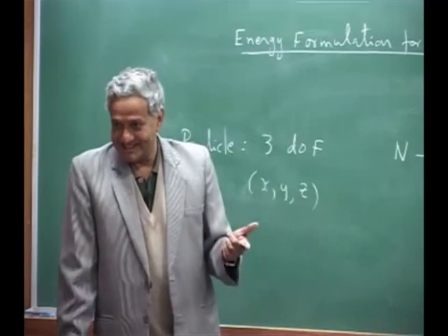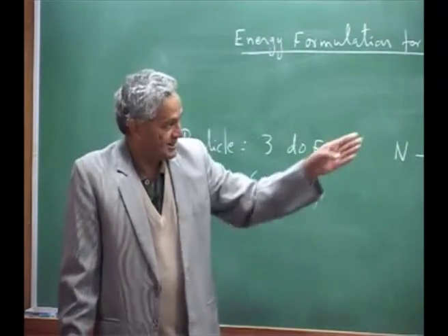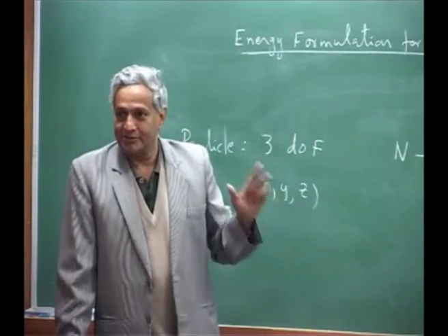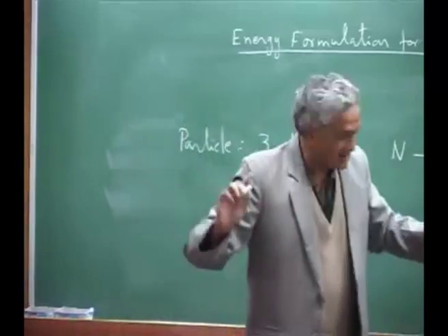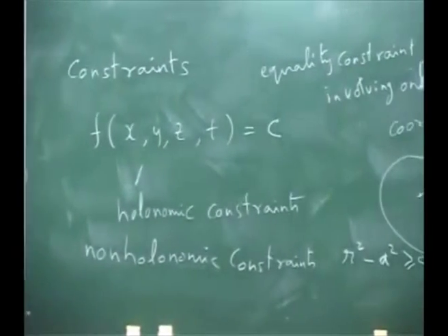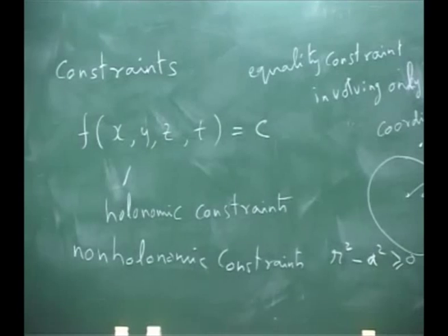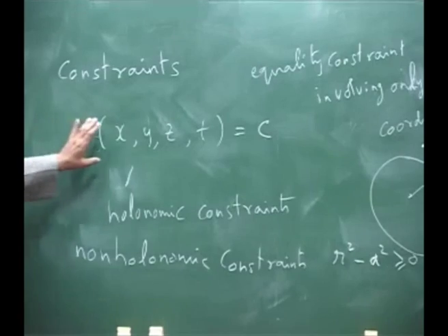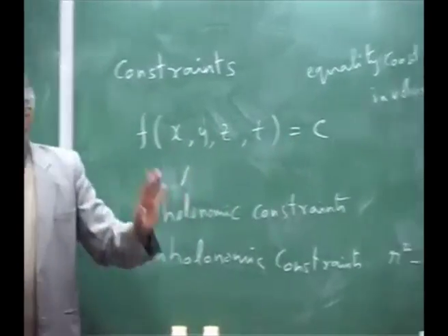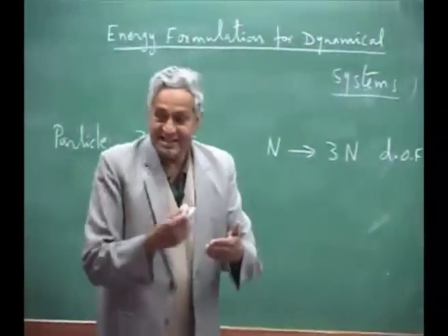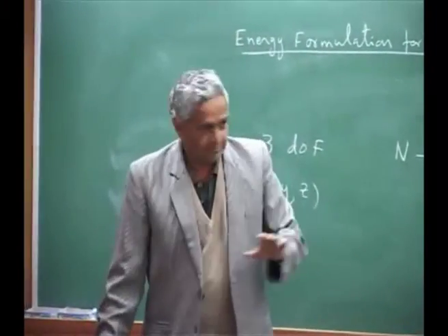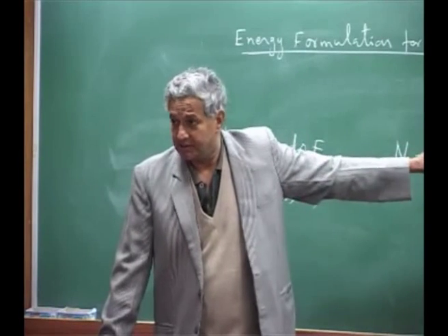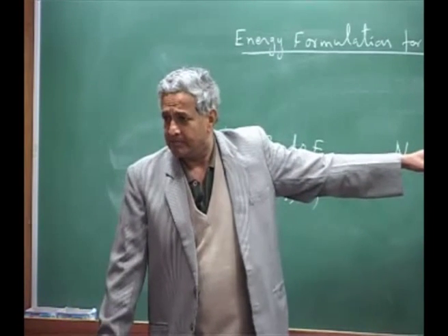Now it is a velocity constraint. Velocity is actually the derivative of the displacement. Those types of constraints are also non-holonomic, because they are not considered as holonomic constraints. Treating them is different. You have to treat them separately. Only holonomic constraints of this type can be easily considered, but the validity of the whole approach is not restricted because of this. Please understand, in many situations it is still applicable.